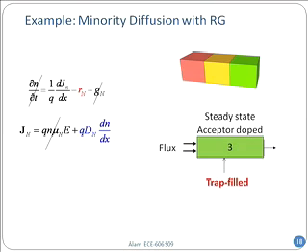Now this time, I cannot take out the recombination because this has a lot of mid-gap trap levels. Copper, gold, these are mid-gap trap levels in silicon. Somehow they have gotten incorporated, so I cannot take it out. The electric field is 0, and correspondingly, the only thing that is remaining is the diffusion term. So I put the second equation in the first one, and you can see that that will give me these two terms.